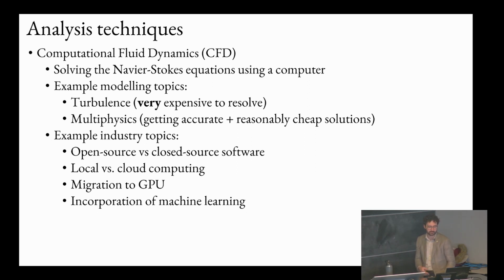Local versus cloud computing. Cloud computing is things like Microsoft Azure, AWS, these cloud services you've heard about. There's a whole HPC side. Because CFD is so expensive, companies want to offload the cost of having to run their own server or buy their own machines, and instead have on-demand access. So now you have to figure out how to run your CFD simulation elsewhere.